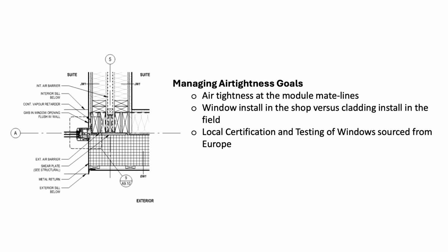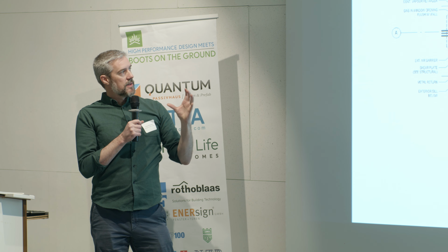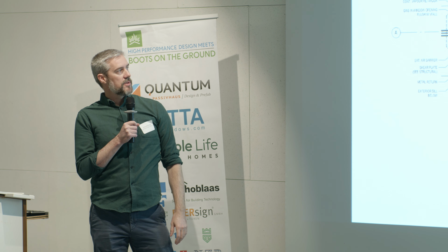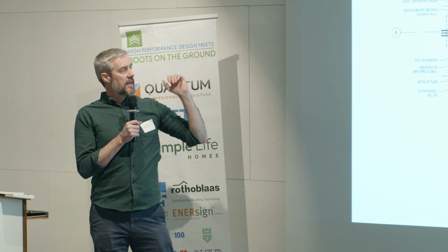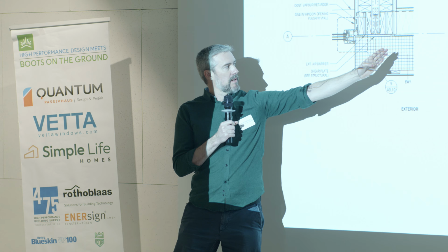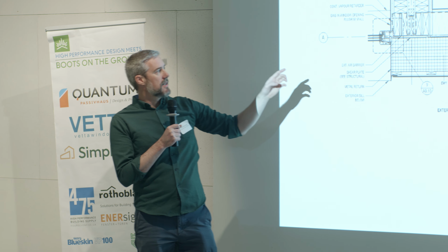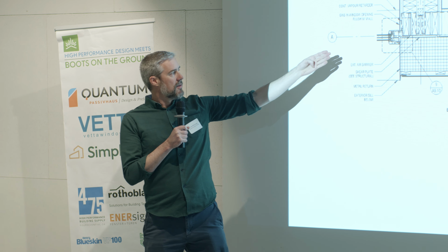So there's a structural component to it, the connection, which is basically as simple as this piece of plywood here, but there are some very strict nailing patterns for that plywood to get the structural integrity in place. And then we had to lap membranes over that. So we had to hold the insulation back by about maybe 6 or 8 inches on either side. In this instance, we had a window right up against it.